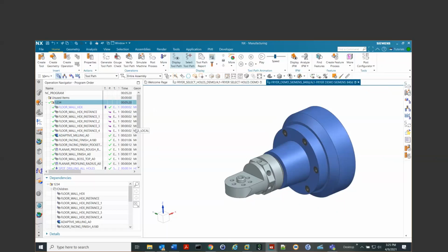So sometimes you will see some OEMs say, oh, this machine has to be purchased and run in a specific unit of measure. This is not a restriction of the SINUMERIK control. My machine, I can bounce between inch and metric. I had my machine in inch, it was running a metric program. I could throw it in metric, run an inch program, or I can flip my unit of measure back and forth. But it is a behavior of the machine.